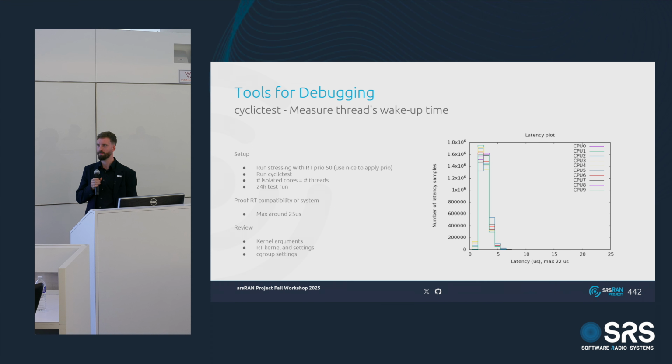What procedures or tools would you use if you were trying to go about debugging something like poor time sync with PTP, or incrementally falling out of sync under a heavy throughput load? Usually first I would have a look at the PTP grandmaster itself. Is it doing what it's supposed to do? If you use an external one, it could be that it's not running well.